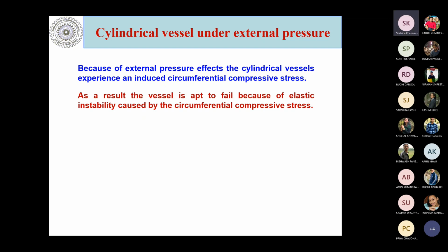So, as a result, the vessel is apt to fail because of the elastic instability caused by circumferential compressive stress. Because this stress is more, the first failure will come from this.